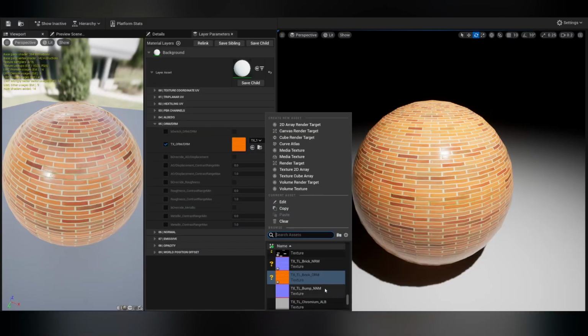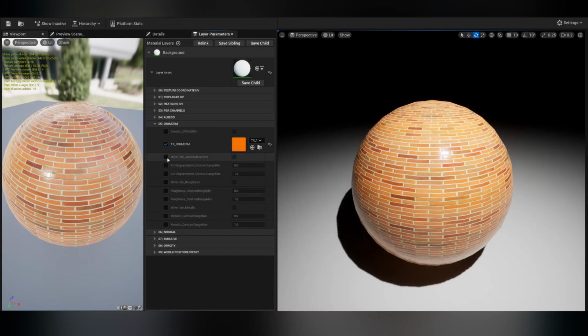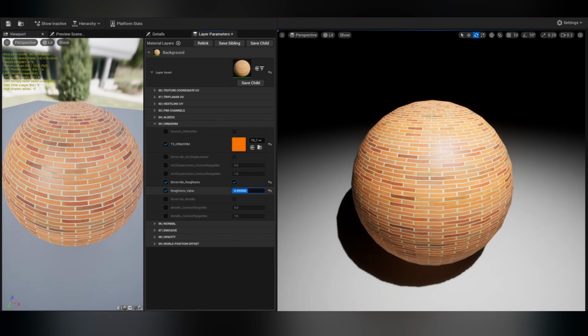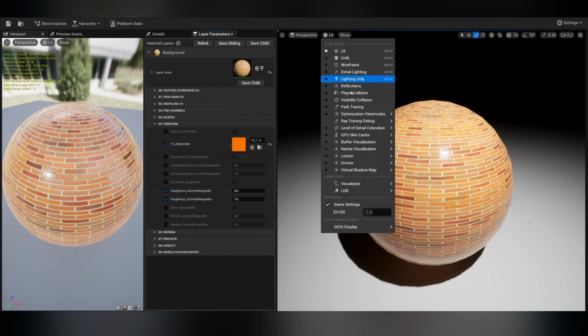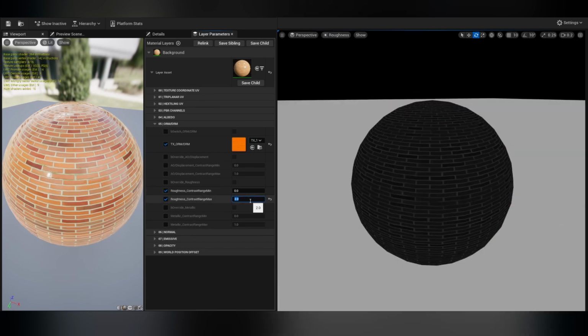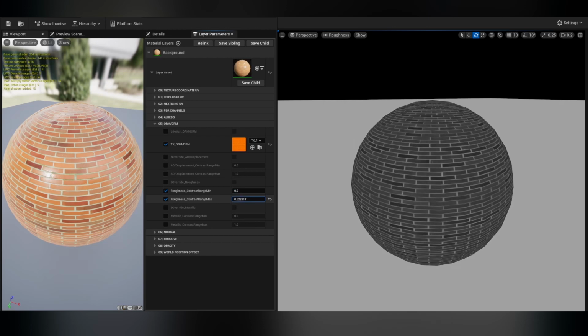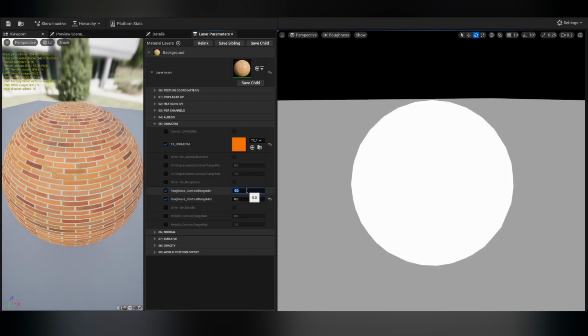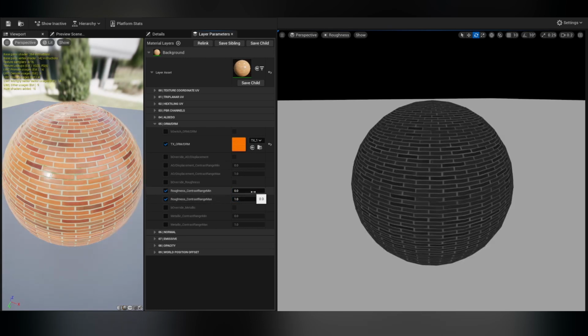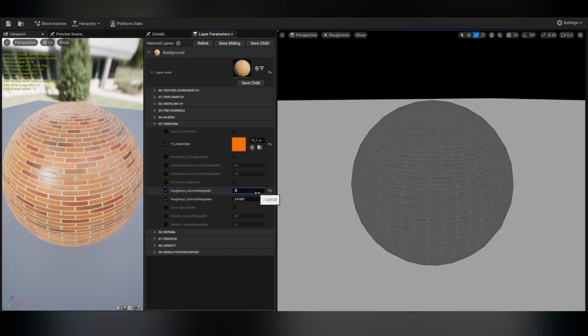ORM/DRM. ORM/DRM textures influence AO/displacement, roughness, and metallic properties. Toggle between ORM and DRM textures using bSwitch ORM/DRM. Customize AO/displacement, roughness, and metallic with override options and contrast controls. Contrast Range Minimum and Maximum are used quite often for many different parameters, so keep in mind that it controls sharpness or softness of any given texture or gradient, as well as the ability to invert the colors.